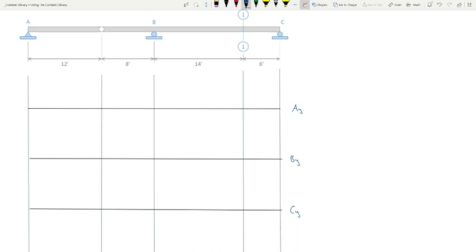It just goes from up 1 at A to 0 at the hinge, right? And what does this look like? It stays 0, right? Nothing. That's 100% right. So the influence line for the reaction at A looks like this, where this is 1.0, that is 0, and if you want, you are more than welcome to label all these as zeros as well. But it's really cool stuff.